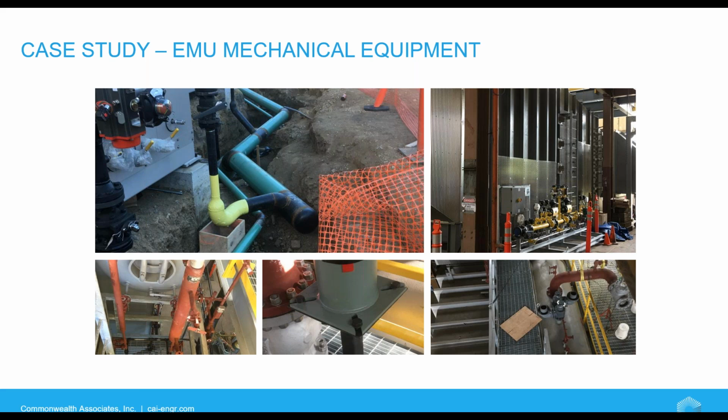To the right of that is the fuel gas supply train to the HRSG burner. Accessibility of valve trains is also an important aspect to keep in mind when laying out a plant. In this case, the valve train is along one of the main walkways in the plant, so maintenance staff walk by there frequently and they can just glance over and verify operation as they walk past. And then along the bottom row are just some, frankly, filler pictures of the steam drum, beautiful pipe support. Those that know me know I started in pipe stress, so I love my pipe supports. And the top of the HRSG with the safety relief valve.